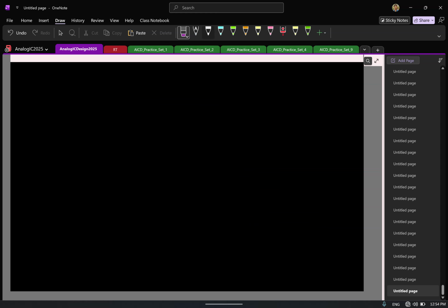So what I'm saying is, if we have a circuit and the input is given to a MOSFET, the noise of the MOSFET can be modeled as an input referred voltage like this. If you find the overall input referred noise for the entire circuit, the contribution of the MOSFET will straight away add like this, and it will have a power spectral density of 4kT gamma by gm.